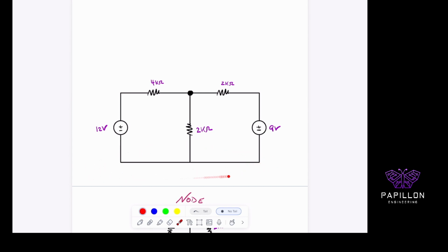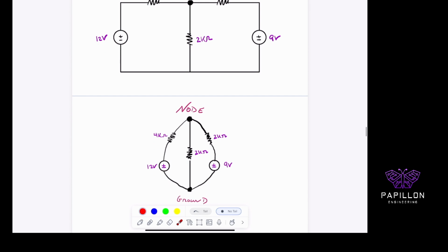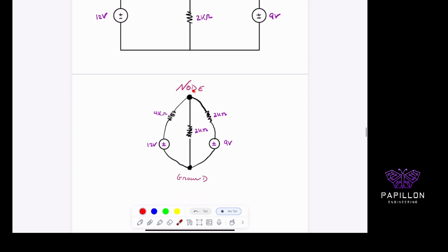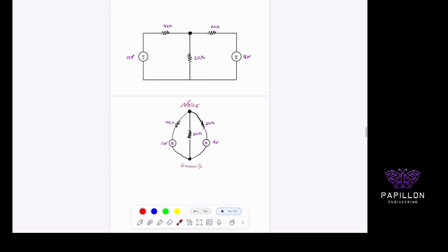So again, depending on how you were taught or what book you're using, sometimes they use a ground, sometimes they don't, as far as nomenclature is concerned. But as far as it looks like, this is how it realistically is. You just have one node, right? You don't have to call this ground every single time, but you just have a node. And now you have a node and your ground. Extremely important. And notice it's the same, I redrew it so you have a better sense of how it looked practically. So if I was in an actual lab or building the circuit, this is how I would actually solder it together. If this is my junction, here would be my ground. Or if I was to wire this in a lab, this is precisely how it looks in my head. Why is that so important? I will show you why in a moment.